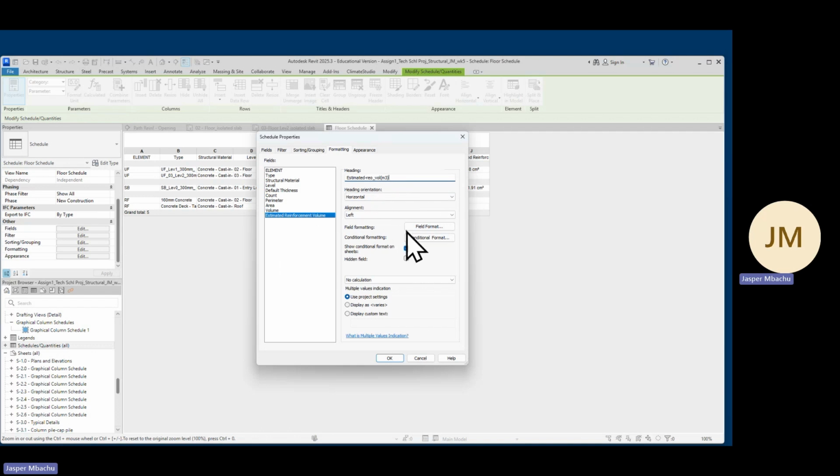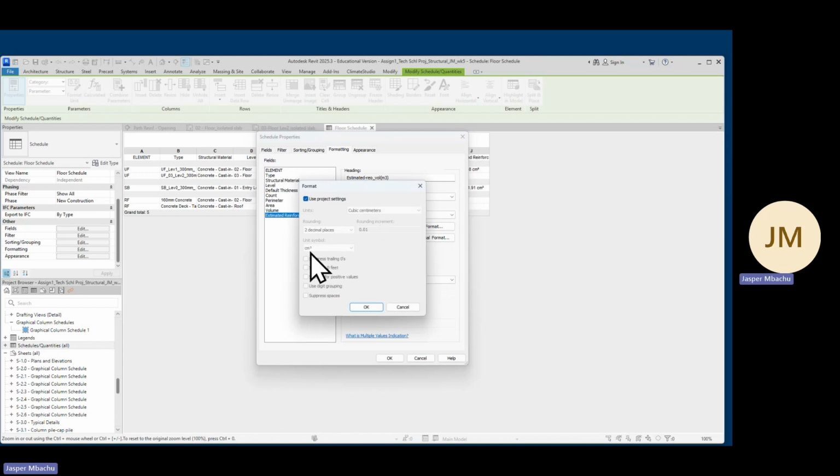All right. Then field format, because the volume is showing here and we don't want this unit of measurement of cubic centimeter. This is why some people don't like Procore. Ozzy, you say Procore is very familiar. So Procore, they will always use this American inches and squares and pounds, you know. So here we want cubic meters, and let 2 decimal places, okay, but no symbol.